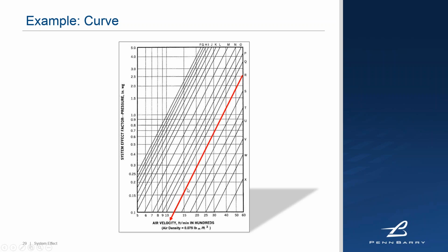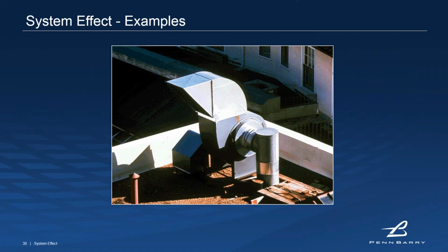So R. And if we look at this, we were at right around 1,000 before in terms of velocity. That hasn't changed. So what that means is that I don't have any system effect as a result of this type of installation. That's what we want. We want to find solutions where a small change like that can be done. Now, we all understand that the installation is going to dictate issues like that.